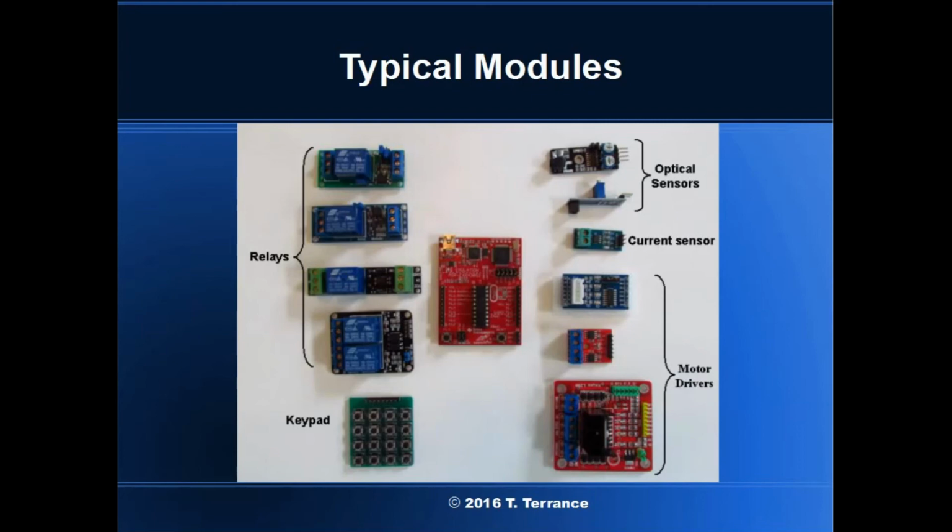One other potential pitfall that you might want to watch out for, electronics engineers call this Fanout. This bit me in the butt on one of my modules, and I should know better. An output pin should only drive 2 to 3 loads, no more, or you get into Fanout trouble.